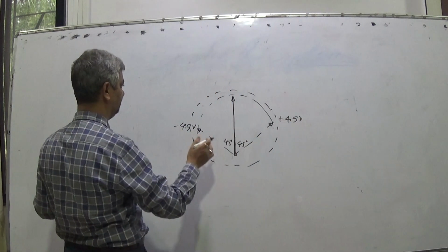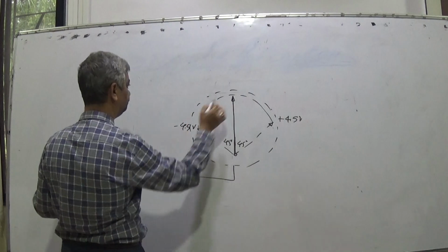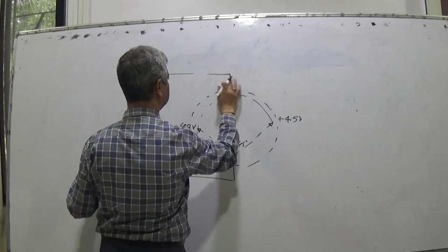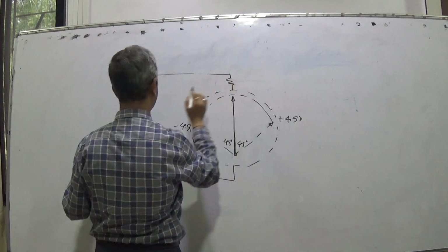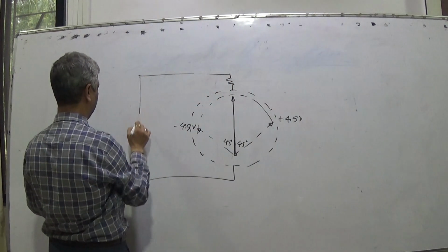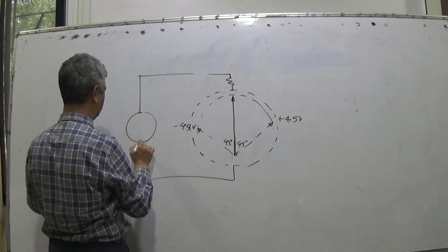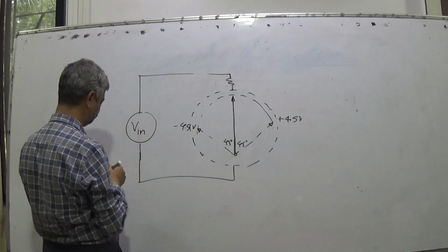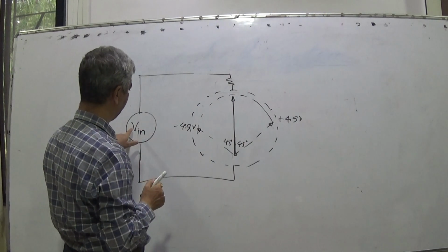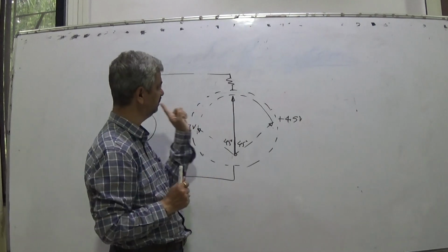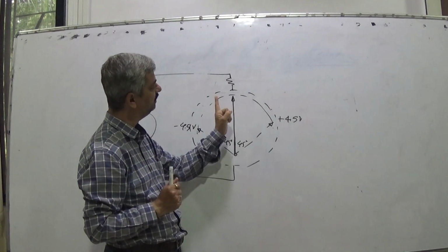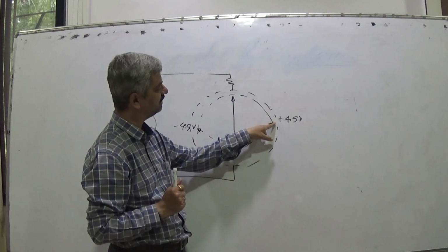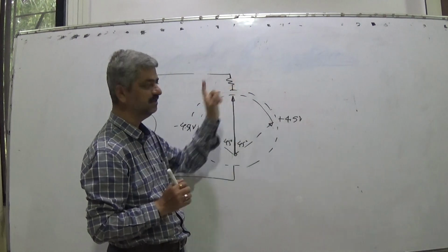So you adjusted, by putting a very proper resistance in series, for voltage input V in, that for plus 4.5 volts the current would be plus IFSD, and that will be marked as plus 4.5 volts. You adjusted this RS suitably.